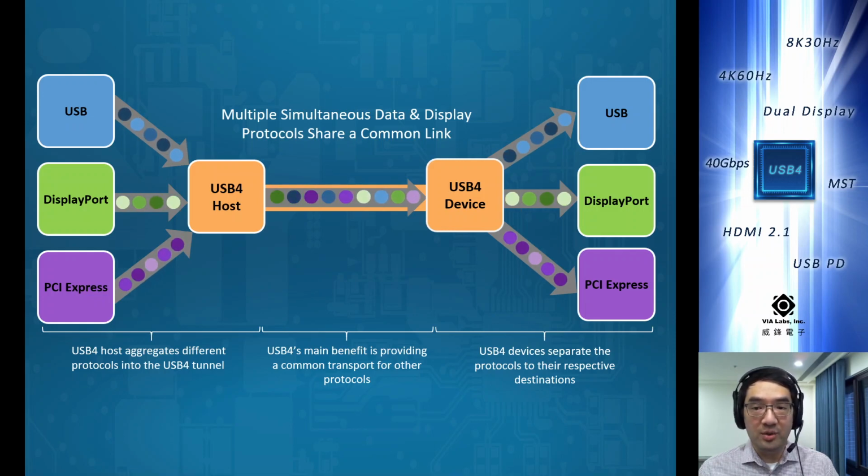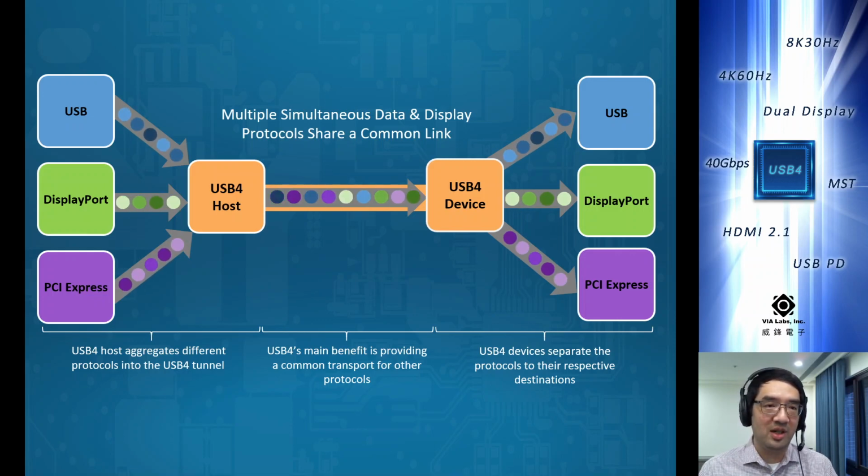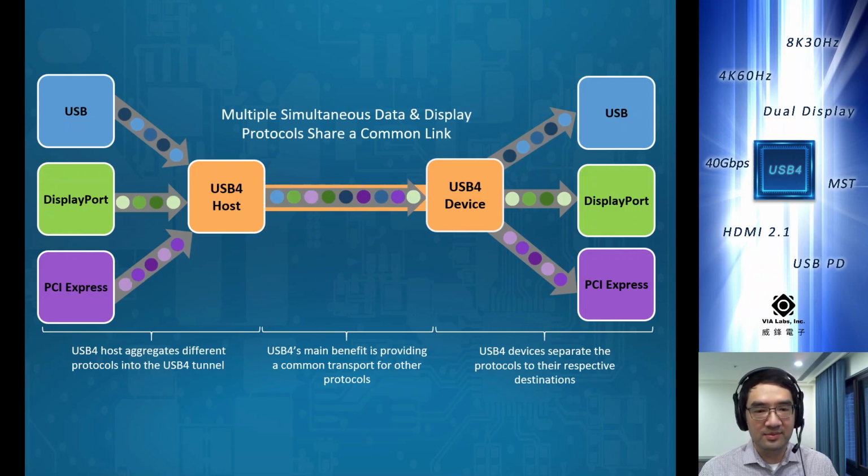So although USB 4 is capable of 20 or 40 gigabits per second of bandwidth, if you're only running, for example, SuperSpeed USB, you'd still be limited to whatever SuperSpeed USB performance levels are. And for most host systems today, that's going to be 10 gigabits per second, although it could be as fast as 20 gigabits per second if the host platform supports USB 3.2 Gen 2x2 tunneling.